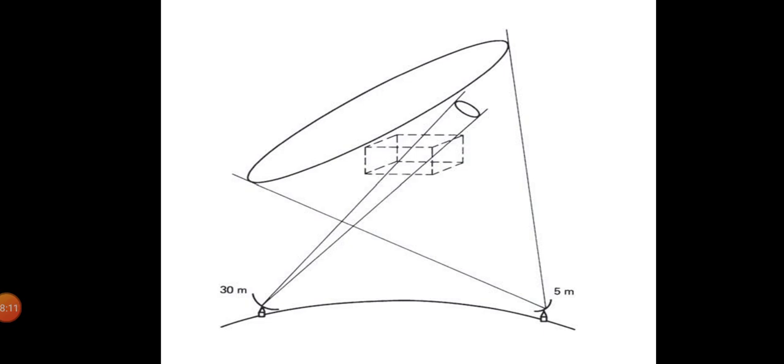Assuming 38,000 km for the slant range, the diameter of the 30 meter beam at the satellite will be about 80 kilometers. And this beam doesn't encompass the whole of the box and therefore could miss the satellite. Such narrow beam antennas therefore must track the satellite. The diameter of the 5 meter antenna beam at the satellite will be about 464 km, and this does encompass the box, so tracking is not required. The positional uncertainty of the satellite also introduces an uncertainty in propagation time, which can be a significant factor in certain types of communication networks.